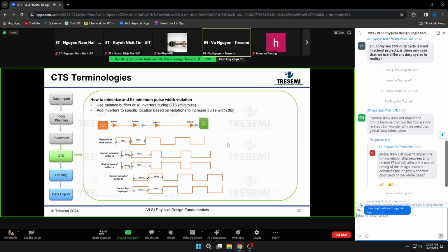This is a very, very good question. At the SoC level, when we architect the chip, this is called the SoC architecture, we define the clock architecture. For a big design, we typically partition into multiple subsystems, and most likely there will be a different clock source for those subsystems. There will be a synchronizer when the clock crosses the boundary.